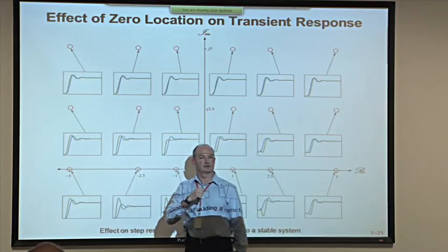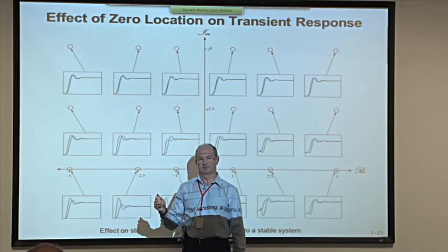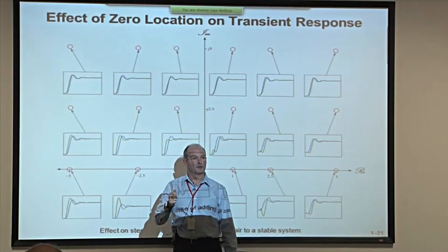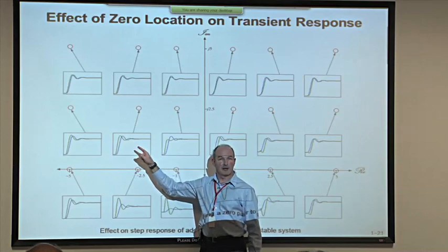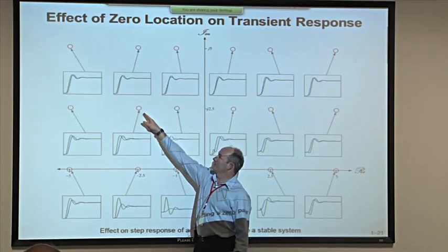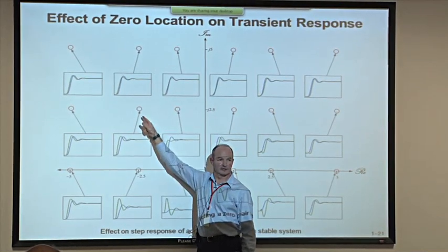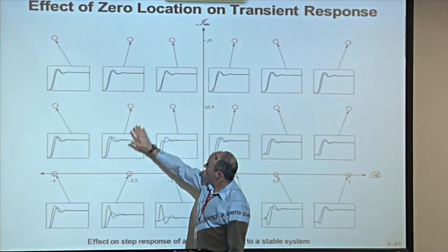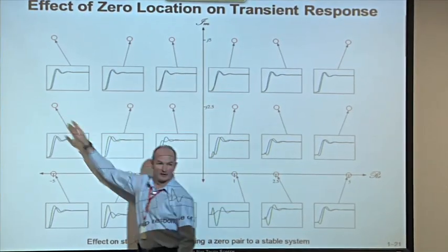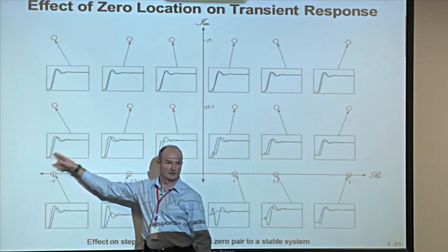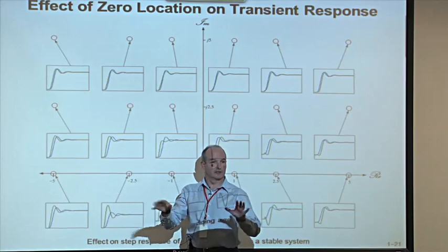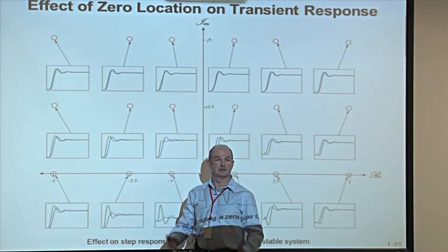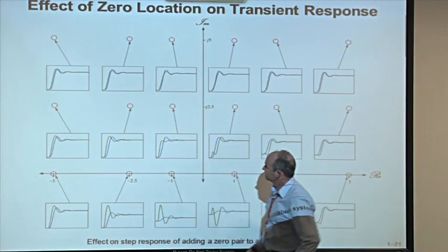That is the response of a system with no zeros in it at all. The other plot, the green plot, is the response of the system with a pair of zeros corresponding to the circle that the graph is connected to. See how it works? So if I move the zero from here to here, the green line indicates the response change. Because the time axis is the same in each of these graphs, we can legitimately compare them and see the effect of changing the zero position.